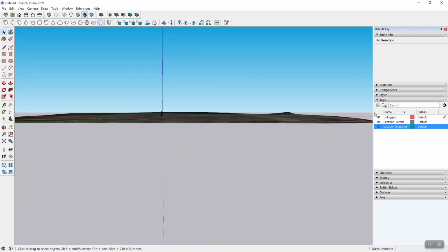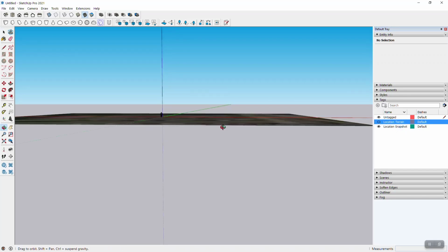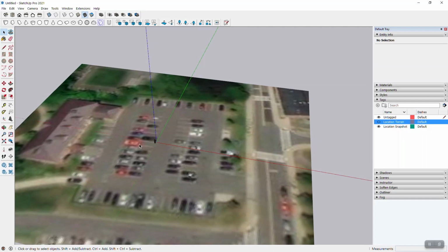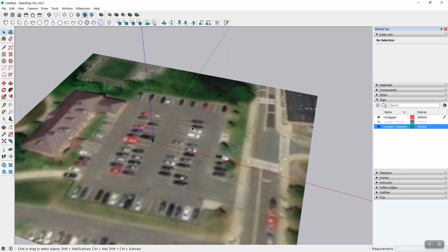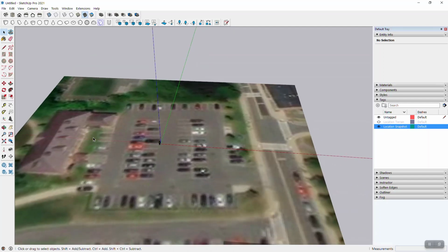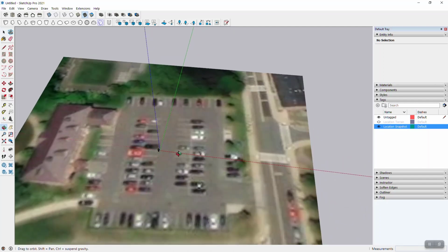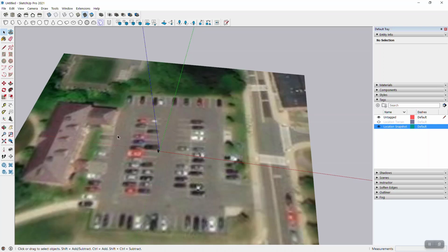And you saw me turning various tags on and off. There are these two tags, and I'm just clicking the little eye button to turn them on and off. So what I usually like to do is to start off with a flat terrain, or basically just the photo, not the terrain at all, because then I can arrange things. Unless the vertical dimension is really crucial, that's a really good starting point. And you can always start that way and then, of course, adjust for vertical and sloping terrains, etc.